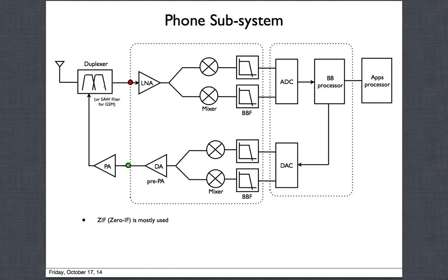Well, the reason we need a filter is, imagine the transmit. This PA could be pumping out power at say 26 dBm. That's like the peak power level for the UMTS standards, almost 24, 26 dBm. You could also be receiving at a different frequency, not the same frequency as TX. So imagine the first one is TX and the second one is RX. The TX is going out at plus 26 dBm, and let's say the receive is minus 110 dBm, the lowest of the lowest signal you're receiving here.